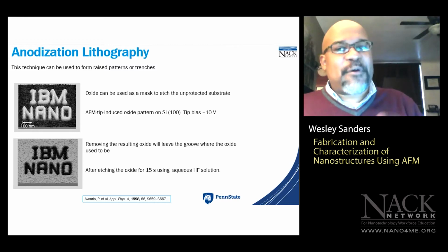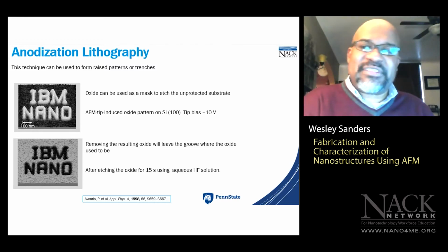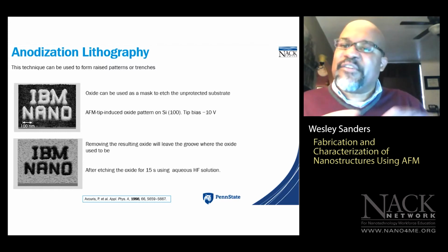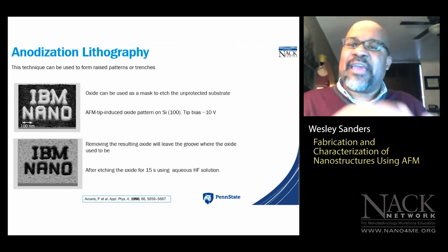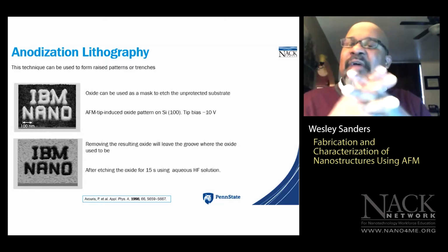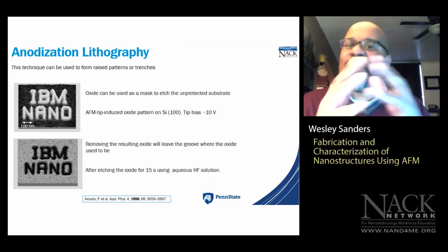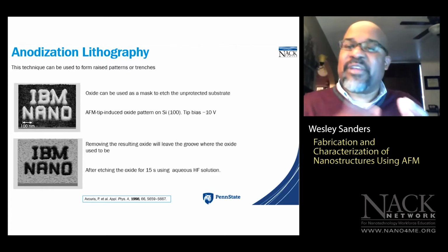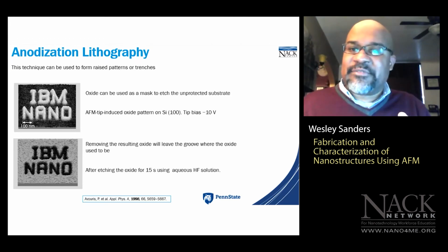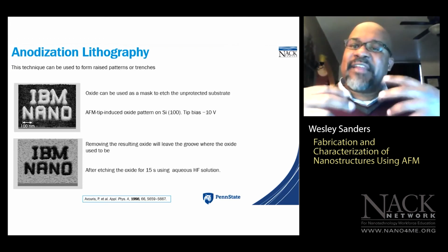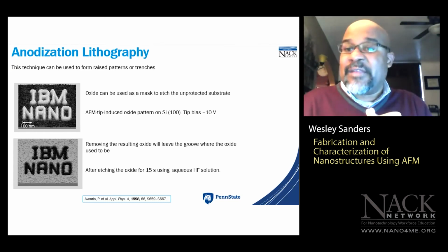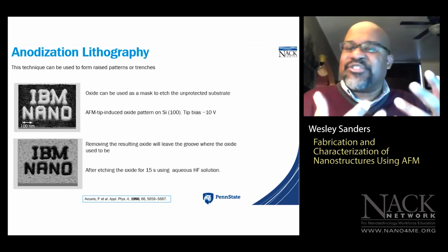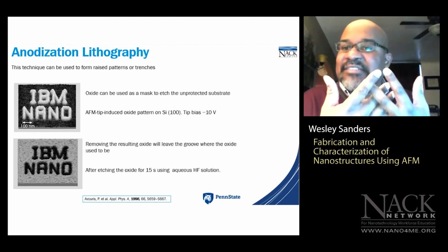So in the case of photolithography, you can have a positive resist or a negative resist. If you have a positive resist, the areas that are exposed to UV light weaken, right? The chemical bonds in those areas are weakened, and those particular areas are rinsed away with a developer solution. Now, in the case of a negative resist, the exposed regions are hardened, right? Because the bonds are strengthened or the polymer cross-links, right?